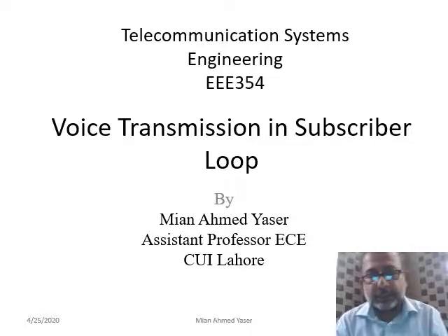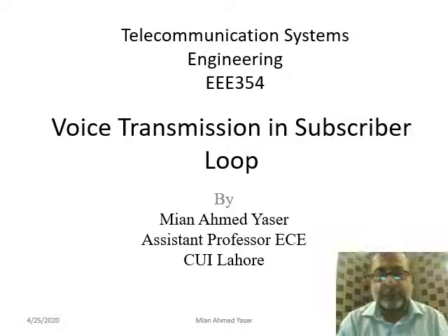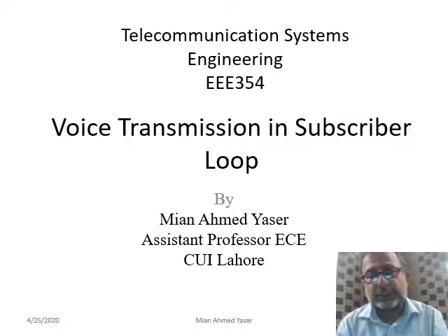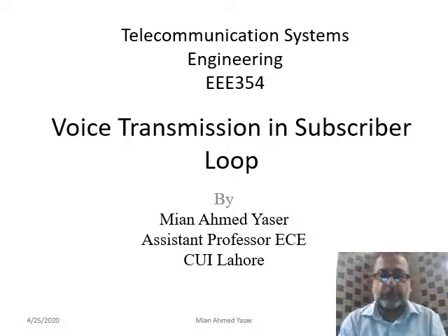Not even that, if we send 200 to 3200 hertz of a band of a person's voice, it is easily intelligible at the other end, because this much band contains a lot of information about the speaker. Not only can we recognize the speech at the other end, we can recognize the speaker also.